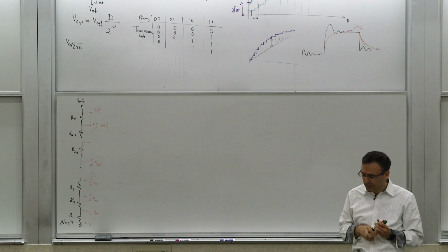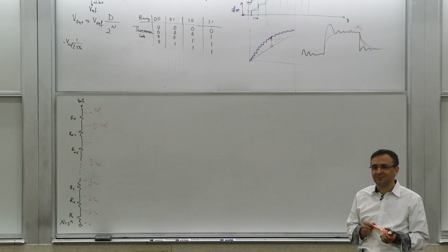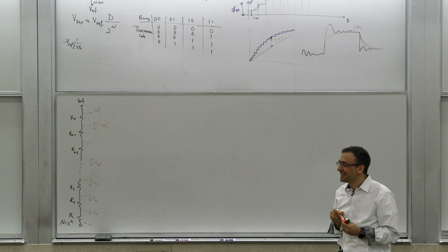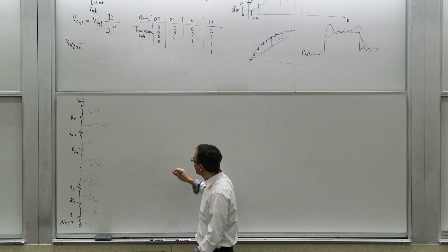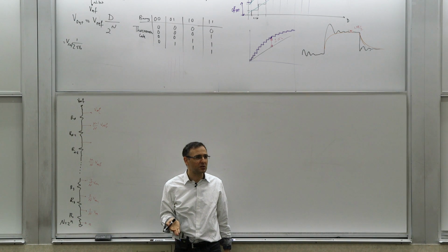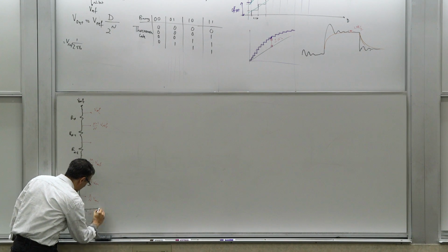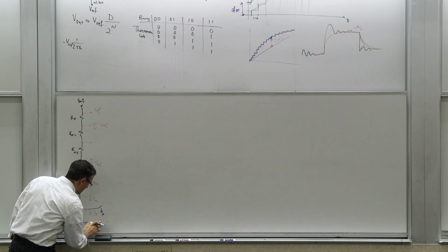If you were to make a very simple D2A out of this, how do we connect it? That's a good question, right? We need to switch it. We need to find a way to, at any point, connect one of these voltages to the output, and which one we connect is determined by the digital value. For example, let's say you have a switch here, determined by B0, and this switch is connected at B0 bar.